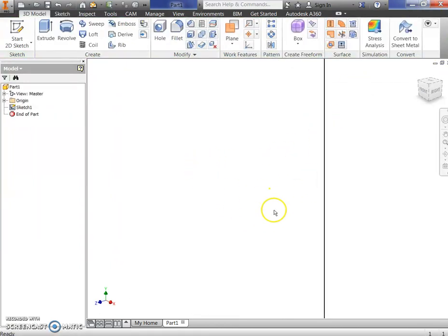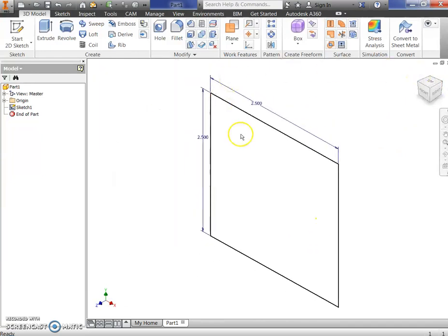So in finish sketch, again, my drawing disappears. So because we are in the 3D view, or we want to make it into a 3D object, I'm going to use this view cube up here, and I'm going to hit this little doghouse. And this little doghouse puts everything exactly right back in the center of my screen so I can see it. And then up on the ribbon tab, I'm going to use the extrude option. So I'm going to click extrude.